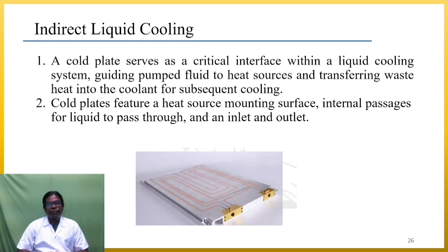A cold plate serves as the critical interface within a liquid cooling system, guiding pumped fluid to heat sources and transferring waste heat into coolant for subsequent cooling. A cold plate features a heat source mounting surface, internal passages for liquid to pass through, and an inlet and outlet.